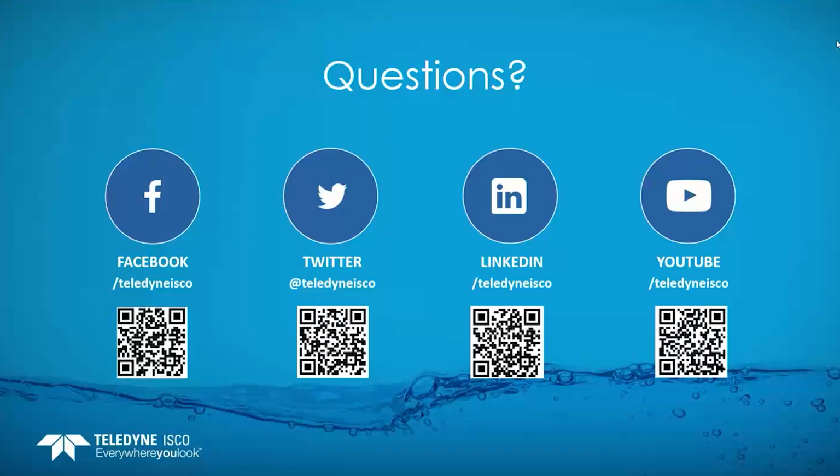Let me see if I can pull it up quick here. So for smaller flumes, you're looking at about a 50% ratio, and then it just kind of goes up in increments of 10 to 60, 70, and 80%, depending on the size of the flume. And if you're over that value, you'll have to do the equation, which is a little bit too much to get into on this platform, but it's a publicly available formula. You have to run everything through. And I believe Darrell can comment on whether or not the meters can do that automatically as well.